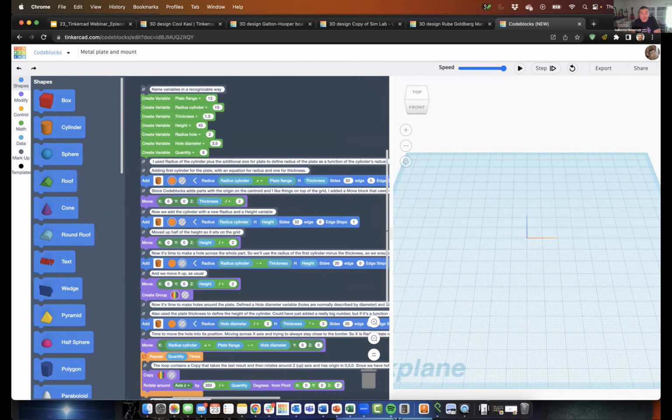And that's the foundation of parametric design. And parametric design in mechanical CAD is definitely very important, right? Also in architecture, if you think about Revit and all those things, everything is moving to that side of the world. And what I did here is an object, this kind of flange tube, where you can define the amount of screws, the size of the plate, the radius, and it has already some kind of relationships between all the variables.